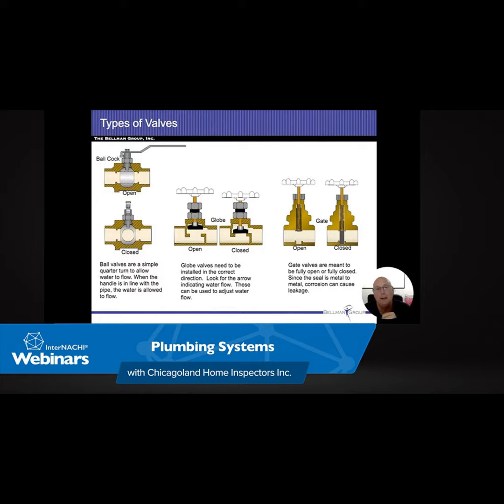Typically what we find on our separations is they're going to put the well in the front of the house and the septic field in the back. But depending on the layout of the house and the land, it might be reversed or it might be on the left and the right. They tend to leave a pretty decent separation. The magic number around here seems to be 75 feet, even though everything typically has a casing on it, so they are typically lined. But everybody just wants to keep a general number.